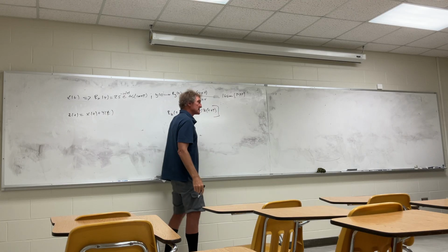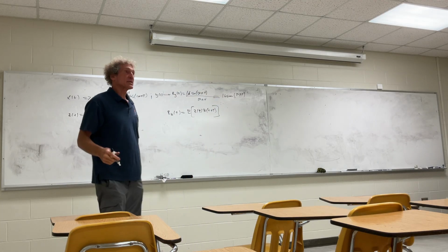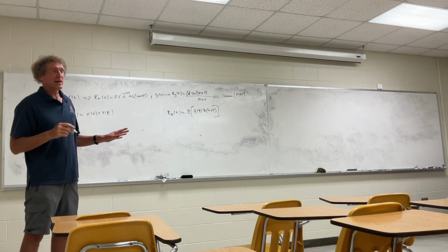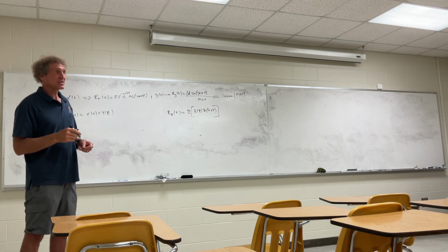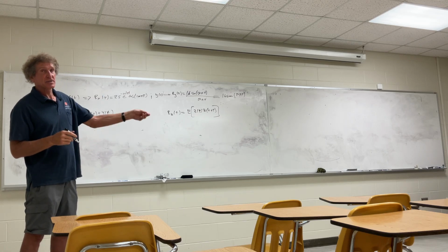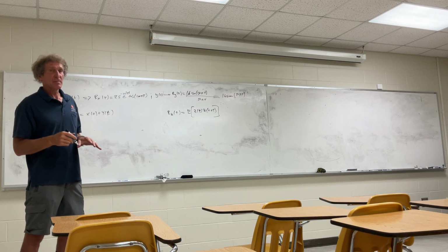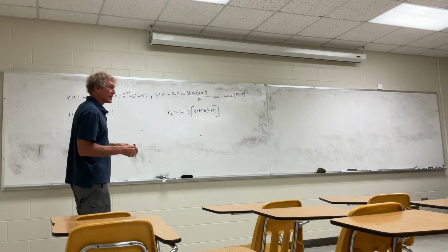Now, I don't think he says it's ergodic in there, but it's assumed ergodic, and it's assumed wide sense stationary. We don't need the ergodic per se, but the nice thing is if it's ergodic, we can use time domain averages as statistical averages, or as that density functions average. Can you understand that, class? Don't make a big deal out of it, just appreciate it. We're gonna get away with everything on this one if we can.